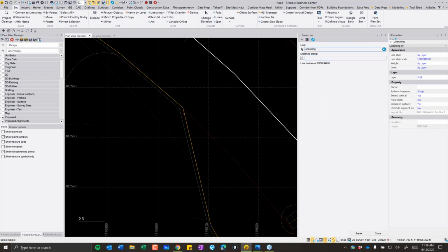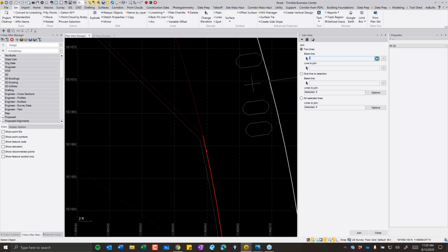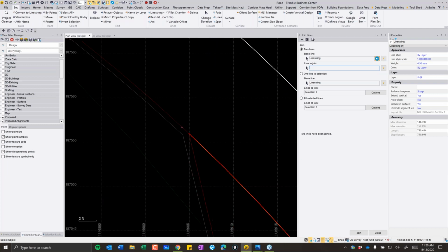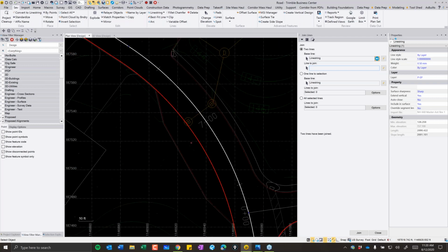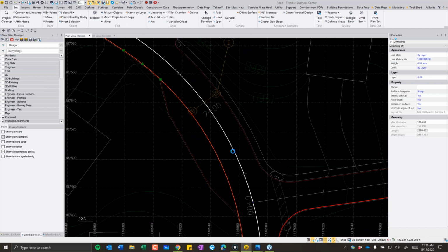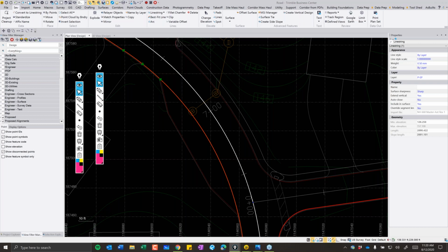Correct. The best way of thinking about it is those are your lanes, no different than you would have your lanes on your corridor that you're using for your instructions. Makes it a lot easier if you have those lines continuous and connected. And I still kind of battle that because from a material standpoint, if I was doing a takeoff, then you would almost think that by having this line come through, you have two areas. You have your roadway and you have your pull off, which isn't incorrect by any means, but it's a kind of weird concept. You would want to keep that all as one area. So now we have this area and then we have our roadway.